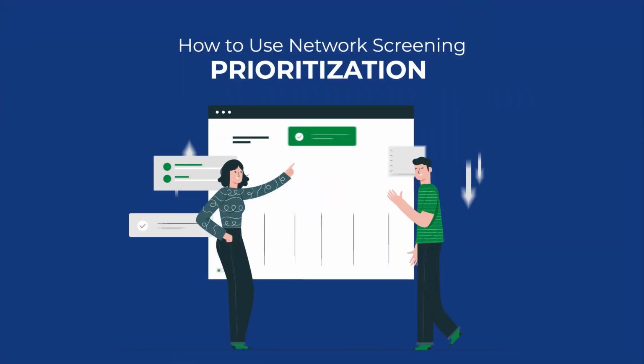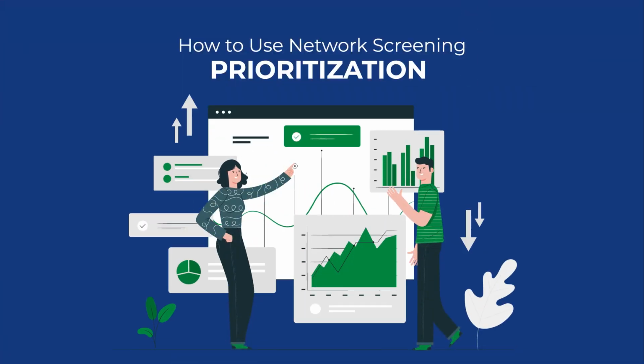These network screening results can help planners and engineers prioritize locations for safety projects with HSIP and Low-Cost Safety Improvement Program, or LSIP, funds. While the network screening lists are not priority lists, the excess crash cost offers useful input for a prioritization matrix.